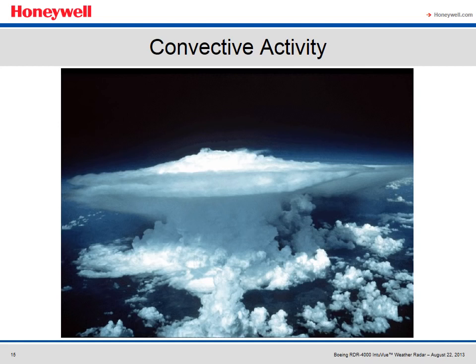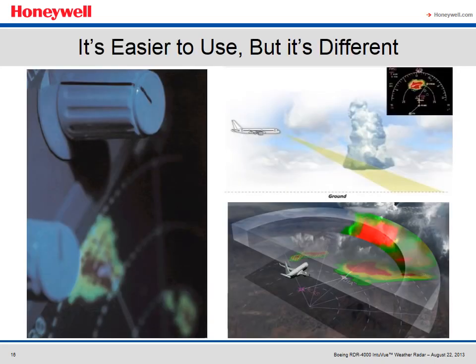At the bottom of the previous chart, there was a note stating the chart was for convective weather. So there is a need to first determine the weather in question is convective for the chart to apply. And so the radar should be used as a tool to detect convective activity, not just rainfall. Convective activity is detected by looking at the vertical development or extent of cells and how much moisture is carried aloft. So altitude is the important third dimension.